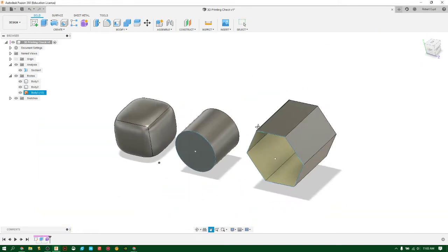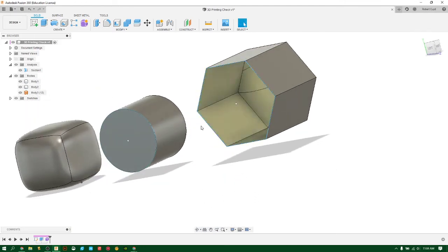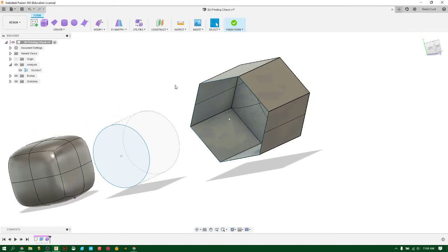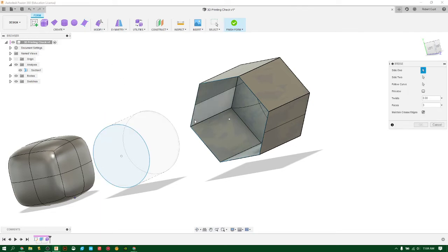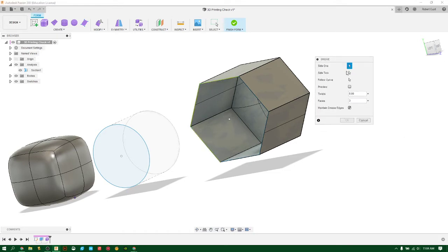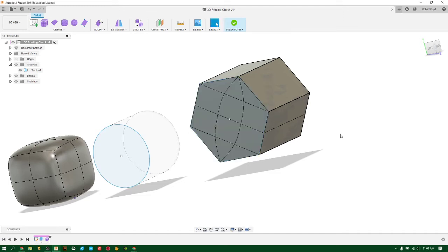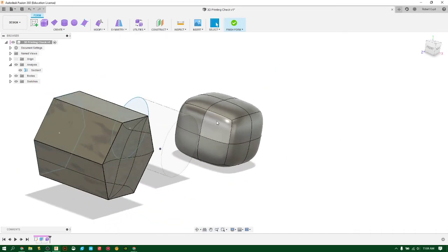So right now the first thing I want to show you is, let's say a lot of you guys are extruding these and you have these open areas that you want to close off. I'm going to go back into form. I'm going to show you guys how to do that real quick because none of the activity showed you how to do that. So I'm going to go to Modify, and I'm going to go to what's called Bridging. You can then select the edges, in this case here, here, and here, and then it says to select the other side. Think of this as mirroring across an object. And you create exactly the same amount of sides on both side 1 and 2. And then you check this little box that says maintain crease edges. What that does is it makes it just go straight across instead of filleting automatically. When I press OK, it basically fills that gap in, and now it looks like a solid piece.